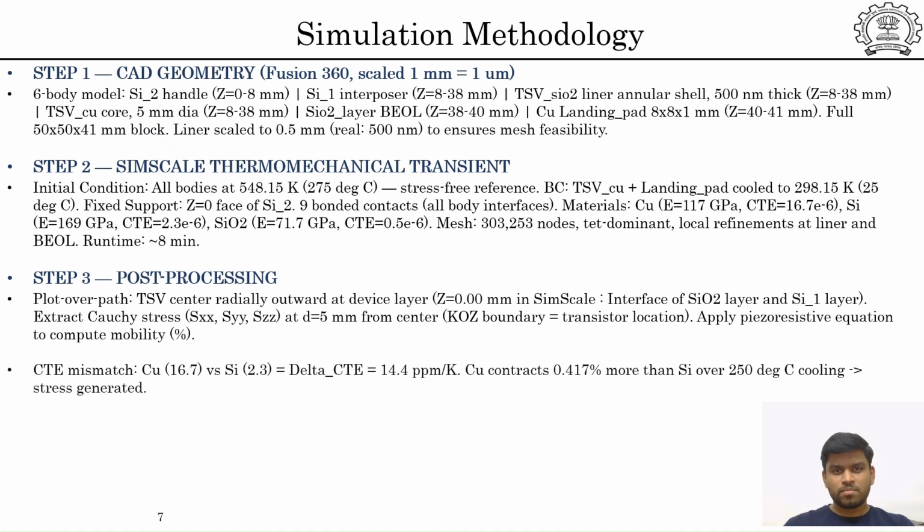So the simulation methodology consists of three steps. Step 1 is gauge geometry, which we have modeled in Fusion 360. As for the second step, we have done the SimScale thermo-mechanical transient analysis, which is cloud-based software. And step 3 is the post-processing, in which we have plotted the graphs for the von Mises stress and Cauchy stress in X, Y, and Z directions.